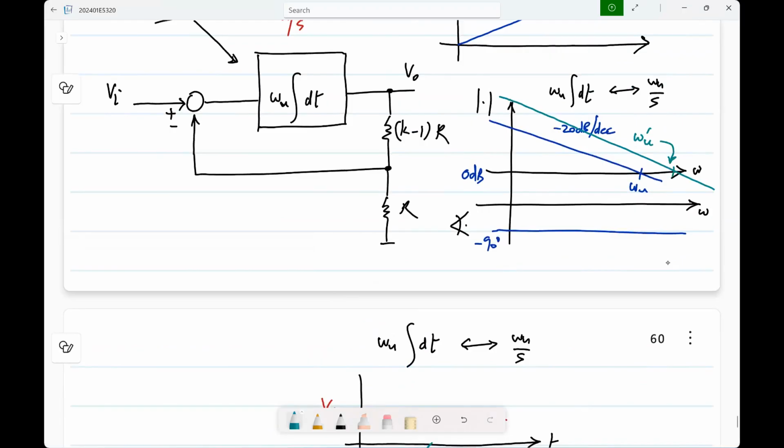So in the frequency domain, the unity gain frequency increases, or in the time domain, the ramp gets more rapid. From the analogy of driving, you can try to change the speed rapidly or slowly. That is characterized by this omega u. If your omega u is large, then you will reach your goal more rapidly, and if your omega u is low, you will reach it more gradually. So it's a measure of how rapidly the integrator tries to drive the output towards the desired value.